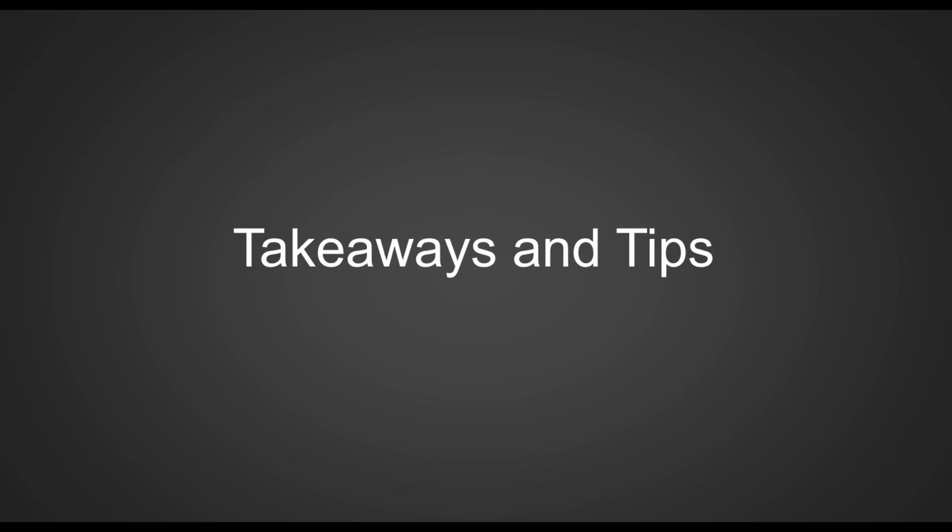Keep in mind to customize your S key as much as you want. Super simple to go to the Customize tab, add commands to that S key. Customize your mouse gesture wheel, of course, as well. Use that D key to bring the confirmation corner to your mouse and not the other way around. Utilize breadcrumbs wherever possible for starting sketches or accessing the fillet command or anything when you click on a feature, even the auto dimension insert, which I showed as well.